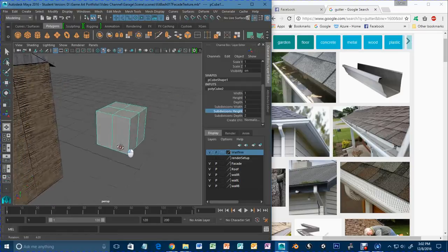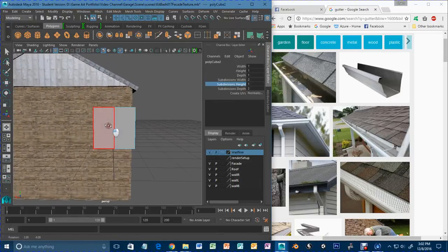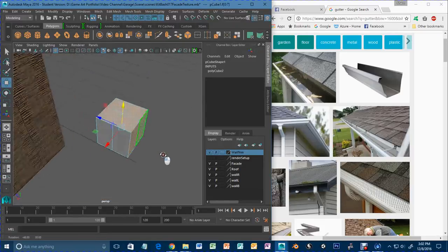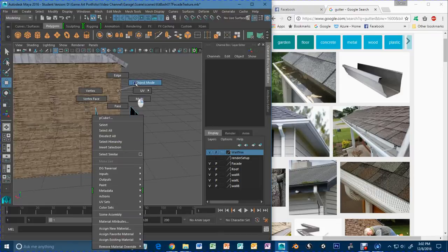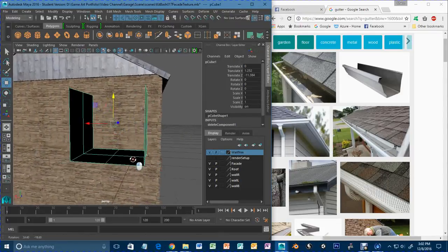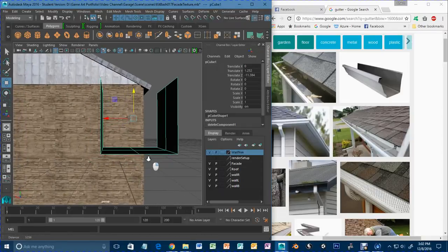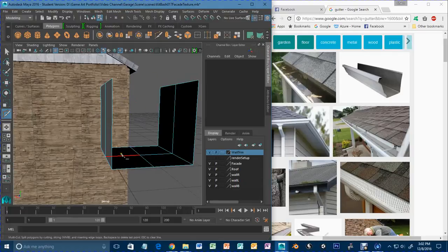And I think I can just go ahead. I'll delete the center right away so we just have the outlying sides like that. And then we'll just kind of do it from here. And then I'll extrude it to give it some thickness. So I'll put my multi-cut tool.